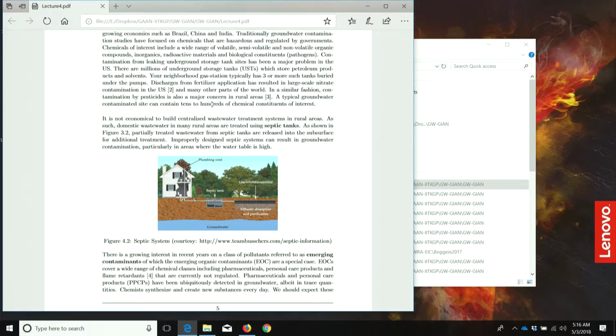And sometimes it's very difficult to do that because you have a house, there's not much space between them. Everybody wants their own septic tank, everybody wants their own well, and there's not enough of the 75 feet to separate these two. So what do you do in that case? I don't have money to put in a deep well. One way to do it is to avoid the aquifer that the septic tank is leaching into. I'll go deeper and get water from a deeper well, right? But a deeper well means an expensive well, so I can't do that.